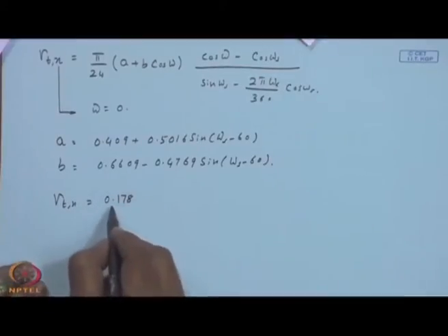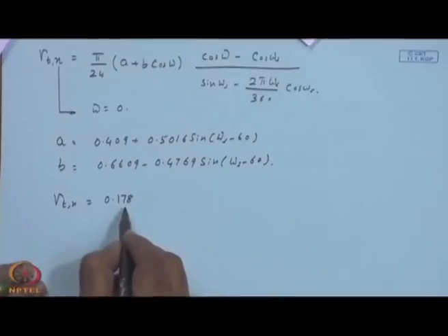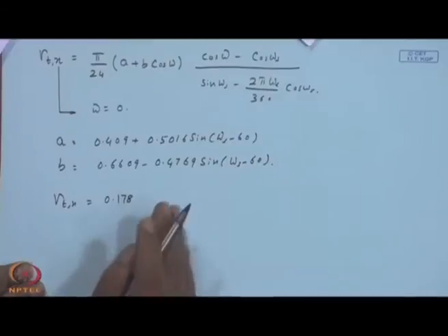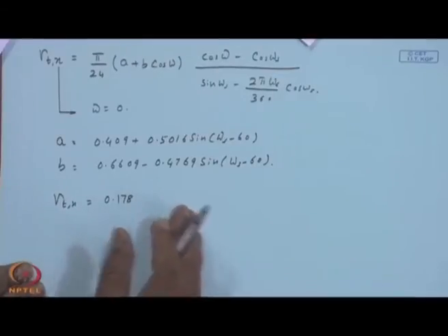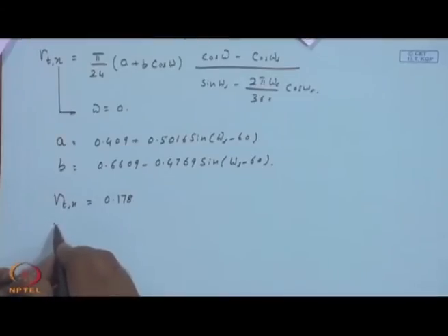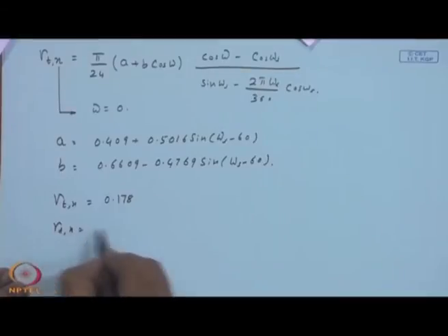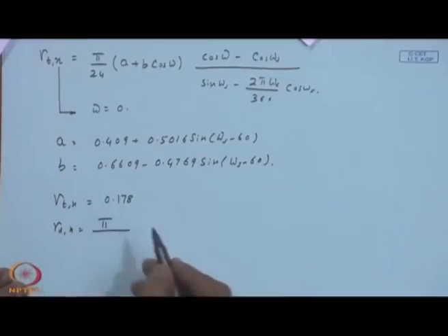This is one way you can check whether the numbers that you get are reasonable or not. For example, r T n should be higher than the proportionate amount around noon time. If there are 10 hours, each one will be 0.1, but around noon time it is almost 0.2. Okay. And r d n is simpler, as the a plus b cos omega is also not there.